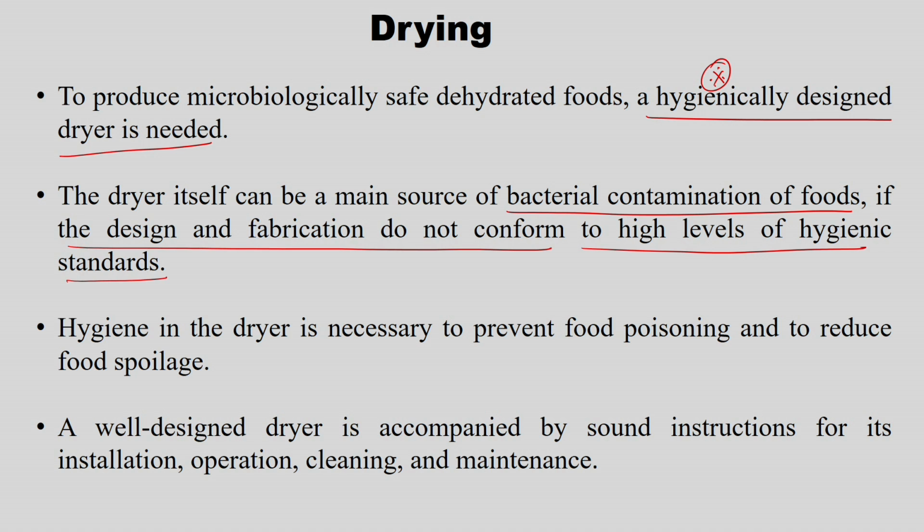Here also, bacterial contamination can occur in the dryer, wherever there is room for crevices or dead areas. So they have to be taken care of while designing itself. Design and fabrication should not leave such crevices or dead areas for bacterial contamination, because if food chunks go and stay there, it adds further bacterial contamination. Hygiene in the dryer is necessary to prevent food poisoning and to reduce food spoilage. So the hygiene part is very much important.